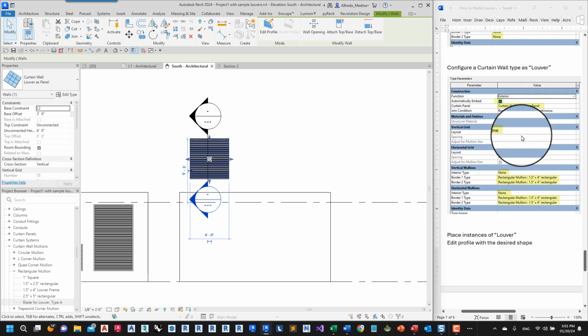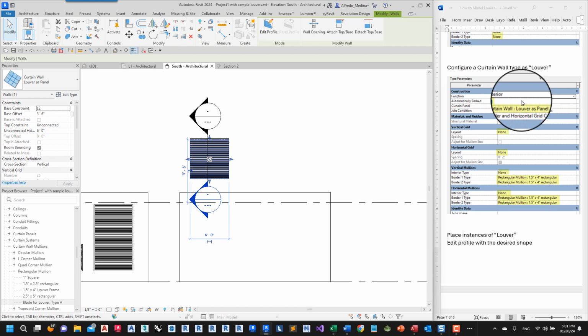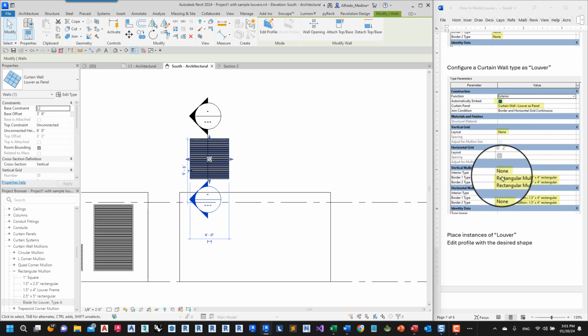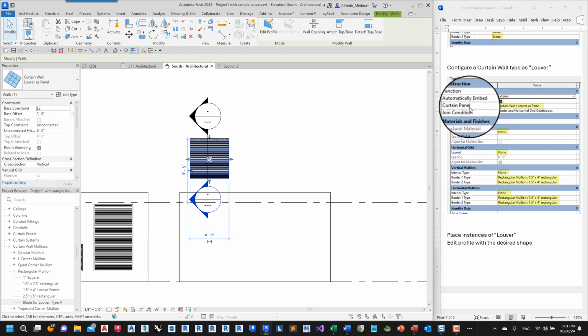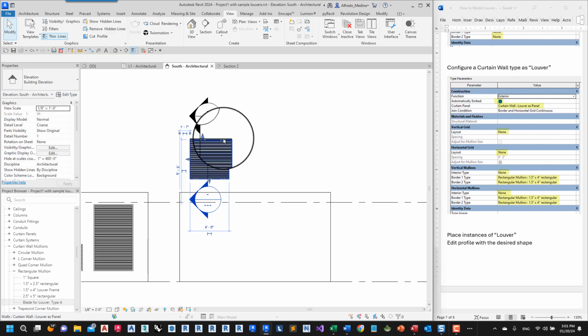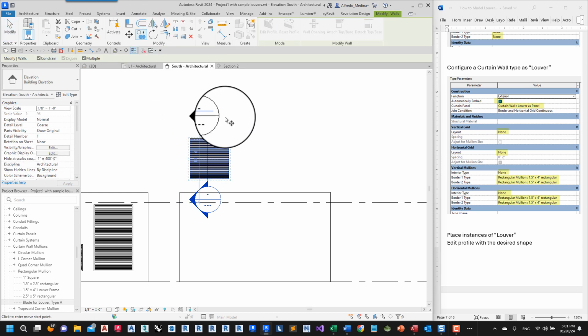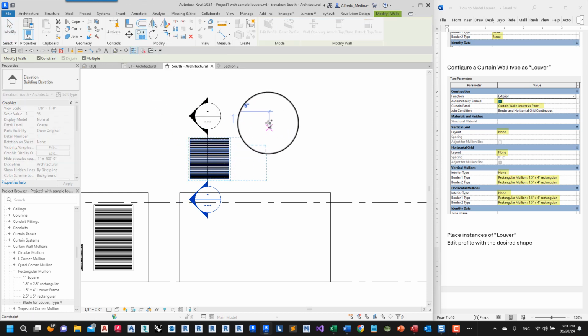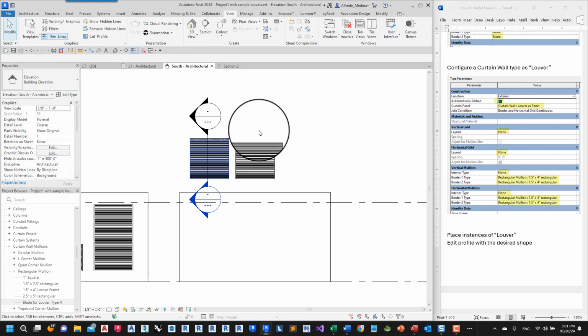Now I want to create another louver that is kind of the opposite. It contains only frames and no horizontals. And it uses this panel as the only curtain panel. Okay, so to do that, we can copy this to the right and do some changes to this.